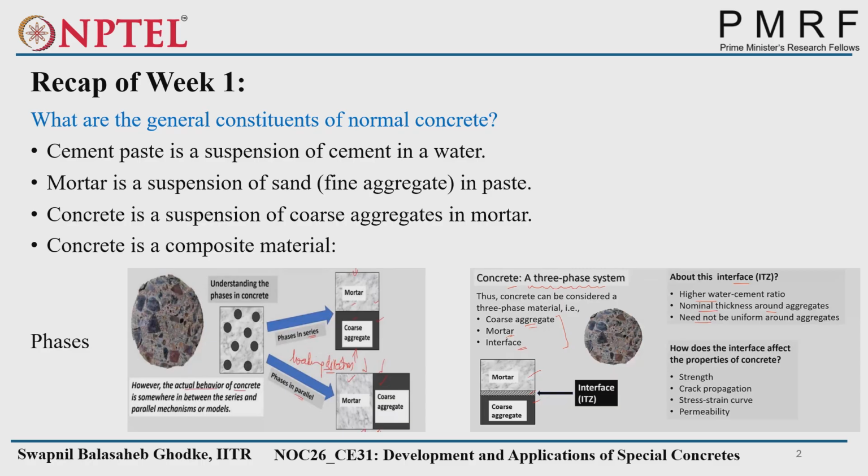Can anyone tell me what happens if the concrete has a higher amount of water content? Bleeding will occur. And what happens with the strength? Yeah, strength decreases. So the same thing happens in the ITZ also, because of the bleeding.